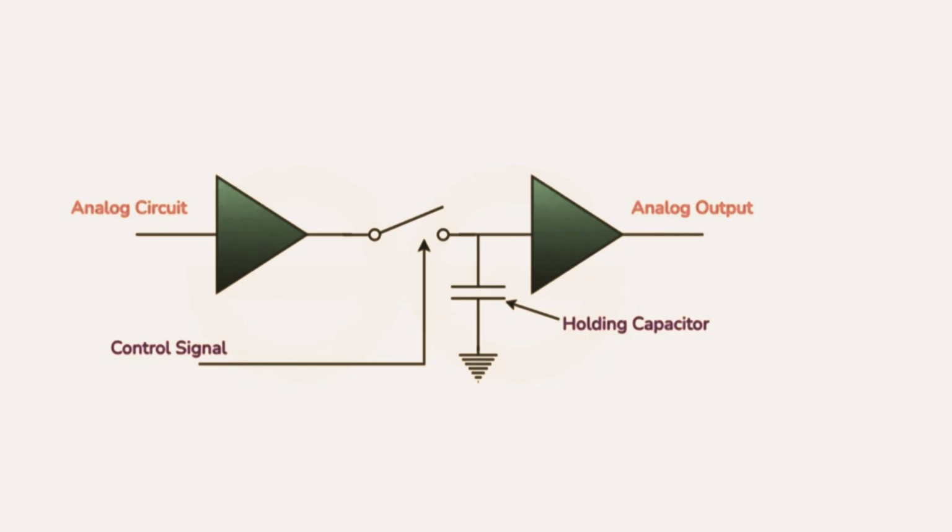And if it can't? If your sensor has a high output impedance, like many simple voltage dividers or some types of sensors, a short sampling time won't be long enough for the capacitor voltage to accurately reach the sensor's voltage. Your readings will be wrong, often lower than they should be. Short times can also sometimes make the reading more susceptible to noise.